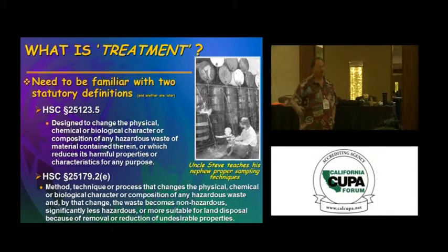So, you have a hazardous waste, and it's pH 0.5. And you need a facility that's going to be taking it off-site, that's accepting it. Like, nah, we don't take anything under 1.5. All right. You throw in a little bit of sodium bicarb, you throw in, carefully, a little bit of some kind of hydroxide, and you bump that pH from 0.5 to 1.5.